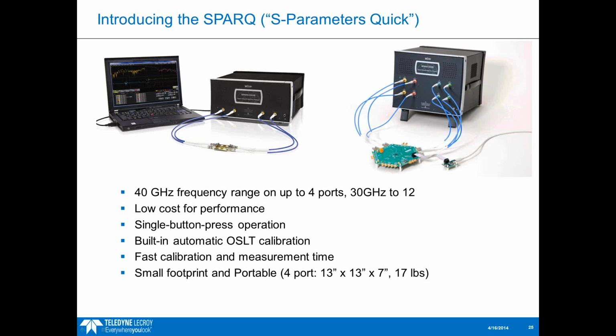Most of the spectral content of the signal that is most important is contained in the first up to the fifth harmonic. So if you have, again, a 5 gigabit per second signal, Nyquist is 2.5 gigahertz, so you would take 5 times that, or 12.5 gigahertz.